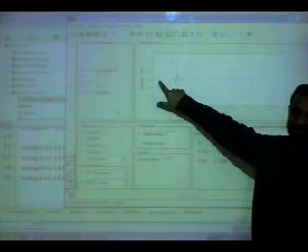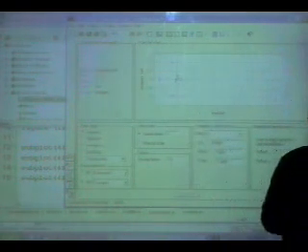Okay, so there are 4 of these. If I say 5, let me see if it is that or not. These are 5. You see, where is the zero? This zero at pi. If you say 5, it will place a zero there. It will always place a zero at pi. Now interesting is, I don't know what MATLAB will do. If I force 5 and ask you to design a high pass filter, let's see whether it complains or will try to do its best.